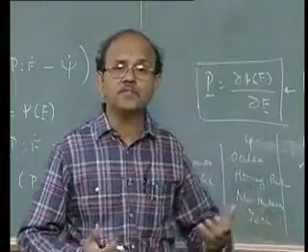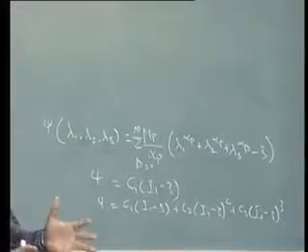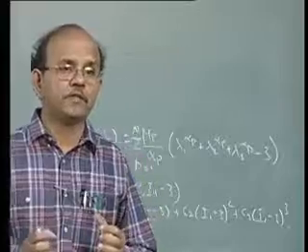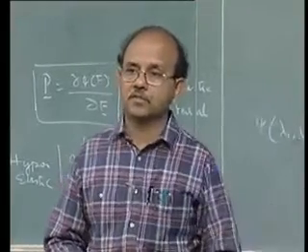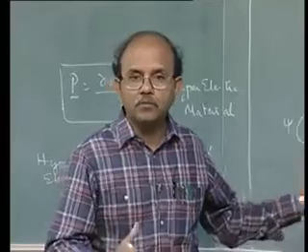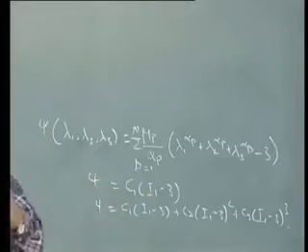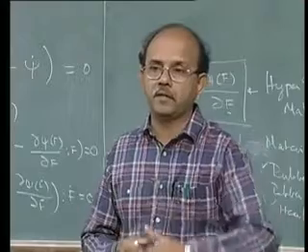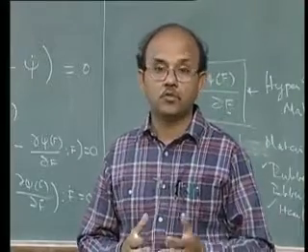How do you get these constants? You do a series of tests. If you do a uniaxial test, you can fit certain constants. Maybe you have to do a biaxial test, and you can improve some of them. Then you may have to do a shear test, and you will get a much better understanding, and so on.